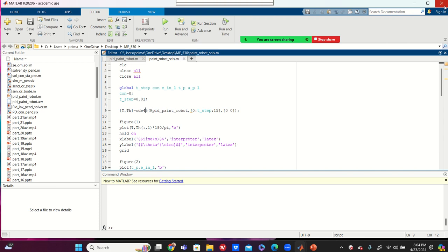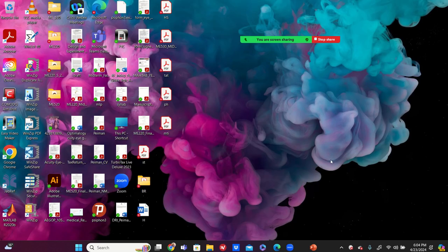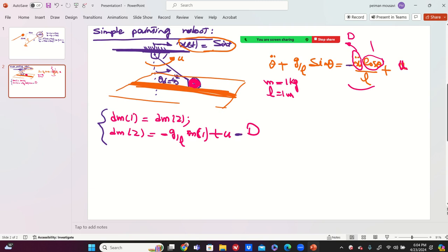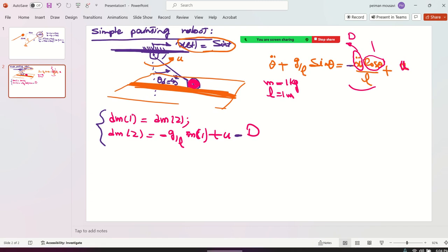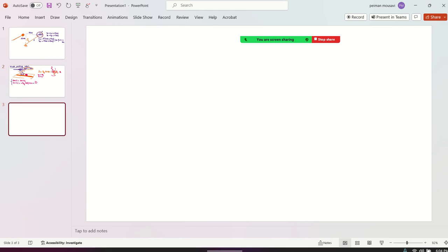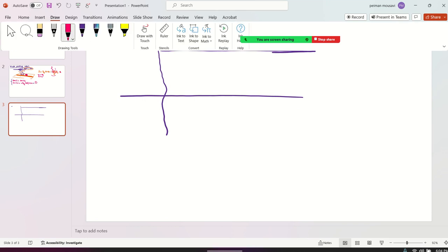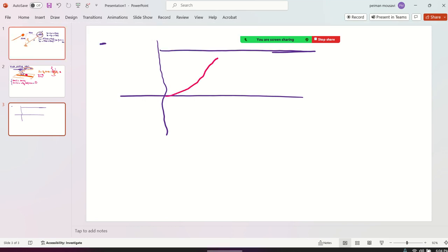So we are done with this. I'm going to share it with you. Okay. Now let's go to what I promised, the Ziegler-Nichols method for designing the PID controller. It's very specific, very narrow, but I'm just hinting at one of them. So it says, if to a control system, guys, you apply a step input, a desirable input, and the output behaves as a delayed first order system like this, we name it an S-shaped response.